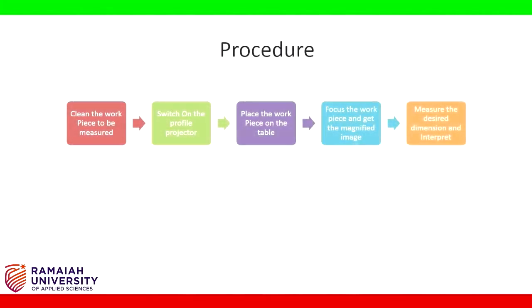Procedure. Clean the workpiece to be measured. Switch on the profile projector. Place the workpiece on the table. Focus the workpiece and get the magnified image. Measure the desired dimension and interpret.